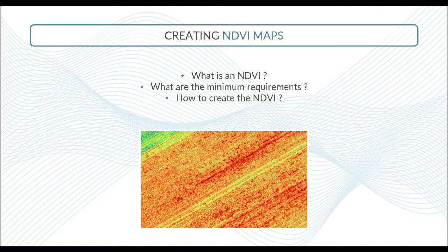There's many ways to calculate NDVI. In Correlator3D, we have a very simple tool to give you a very quick NDVI, so you can have an idea of a vegetation index over your project. And so the resulting output will be a color-coded image like this, where in this instance a very high red value would mean that there is high contrast between the red and the infrared, meaning probably healthy vegetation, and on the opposite, blue would mean maybe no vegetation at all.